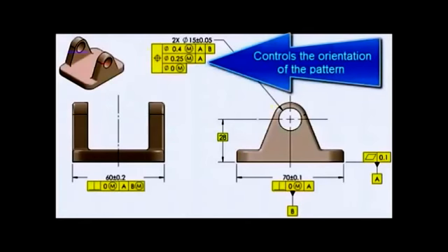Since datum feature A has been brought down and referenced in this second segment, datum feature references in the lower segments control orientation. So you'll notice that the gauge pins have to remain parallel to the plane established by A as you inspect for this 0.25 positional tolerance.